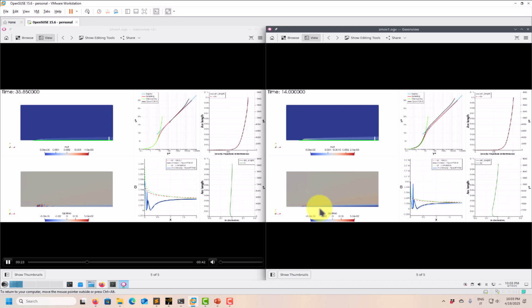So we're losing the fluctuation. Instead, look at that, the wall modeling, sorry, okay, you still capture that fluctuation there, and you see it here in your friction coefficient signal. And well, another strange behavior, okay, so this doesn't mean that the Spalart-Allmaras is wrong or K omega is wrong, it depends on what is happening. The mesh, numerics, coefficients, many variables are coming into play.